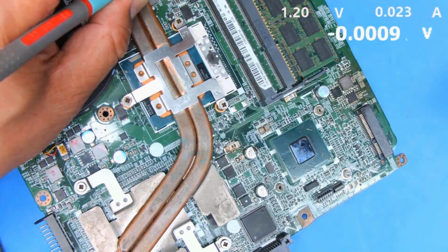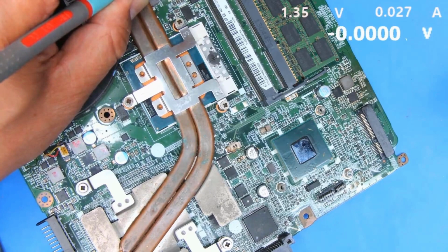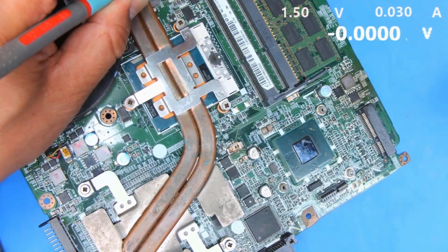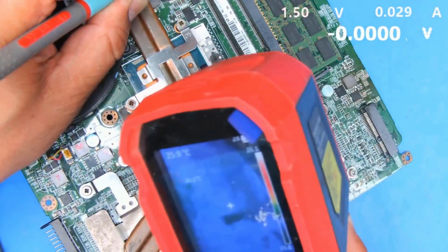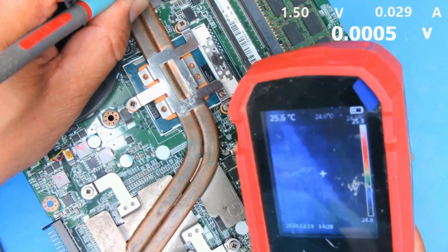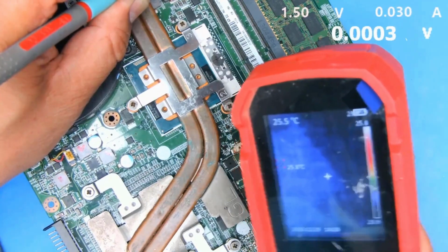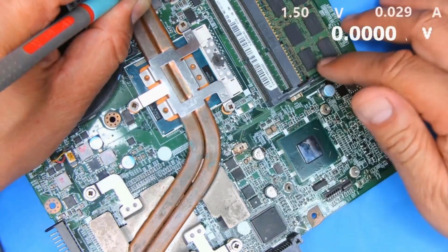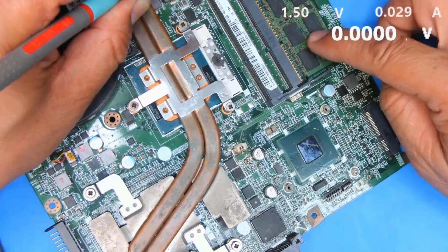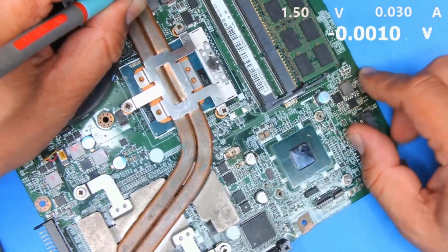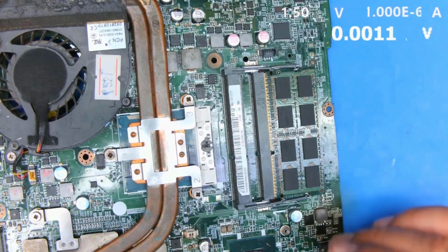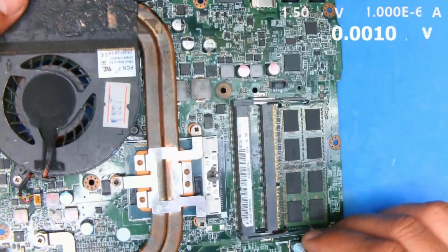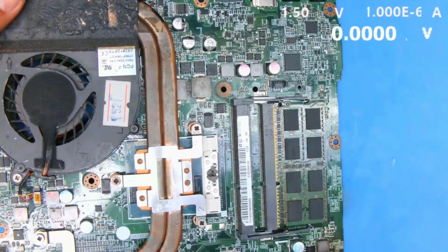Let's increase the voltage to about 1.35 volts. The current will go up a bit, see, just a little, 1.5. So at 1.5 volts, the current is 0.03 amps, which should cause new heat, but it doesn't really happen. Notice that this method doesn't work very well if you increase the voltage more than this, the heat will occur at the RAM instead, because all the power is running into the load at the RAM. Therefore, supplying power or using a power stick is not suitable for finding the shorted component or highlighting the short. Using a power stick is not as effective.